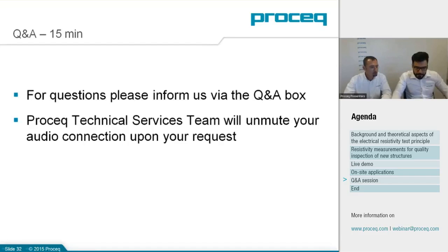Fantastic. Now, if a lab sample has dried out, having not been cured according to the test method, do you have any experience attempting to resaturate the sample to the original condition? If so, how did you resaturate the sample? Well, of course, you can put it in lime water or in the moist room, but it's not a matter of just allowing the water or the moisture in, because the curing condition is different. It's not that you can pick up where you left off. So you can reiterate it and measure it, but do not assimilate that behavior to what was cured properly.